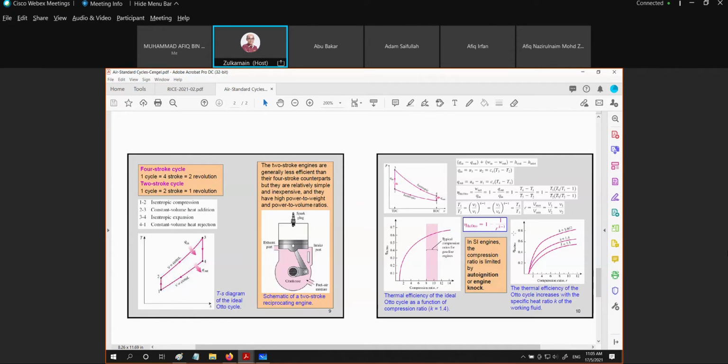But as I have discussed before, the R value is always constrained by the type of fuel being used. Although we can see that if we increase the compression ratio, we might increase the thermal efficiency of the Otto cycle, it is not as easy as that. It depends on the ignition temperature or the flame temperature of the combustion of the fuel.